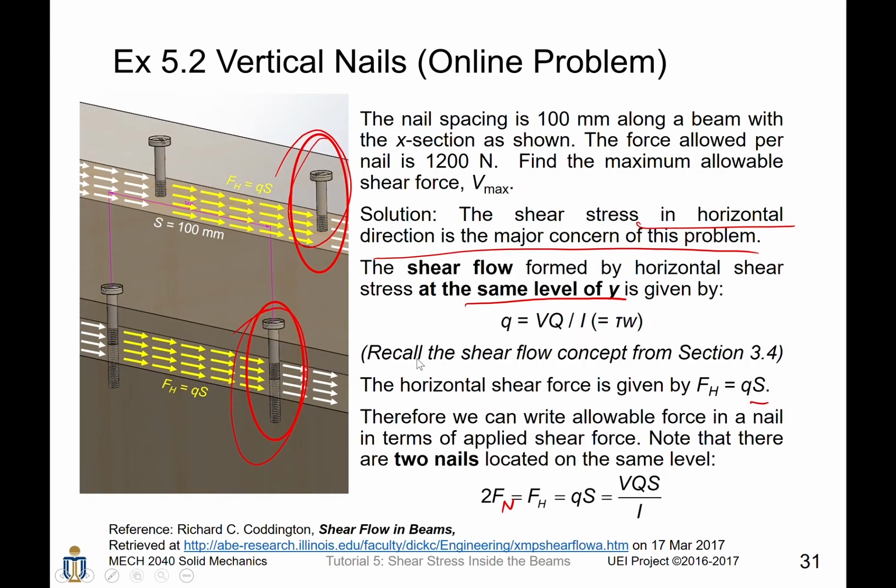So it is also the failure mode of the nails inside the box beam, as was shown just now. For this box beam, there is a distributed load like this, and then at this horizontal surface there is a shear flow, which is providing a relatively large shear force to this nail. And for the nail below this boundary, there is also a distribution of shear stress.